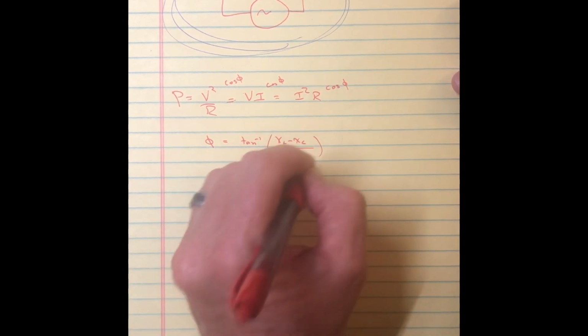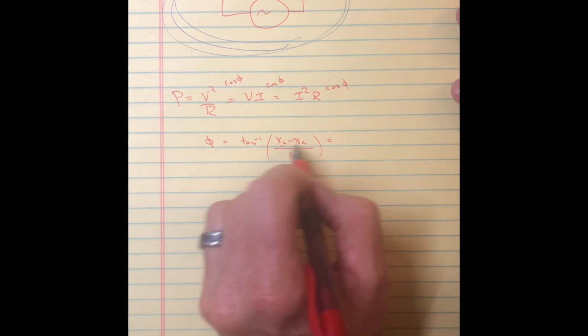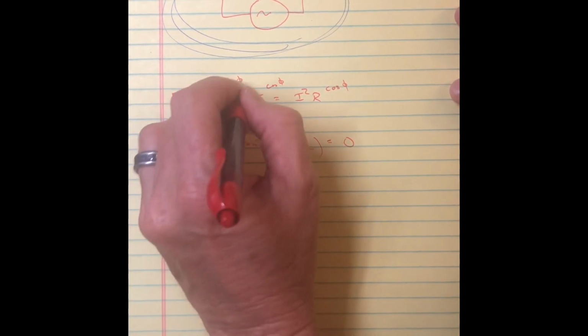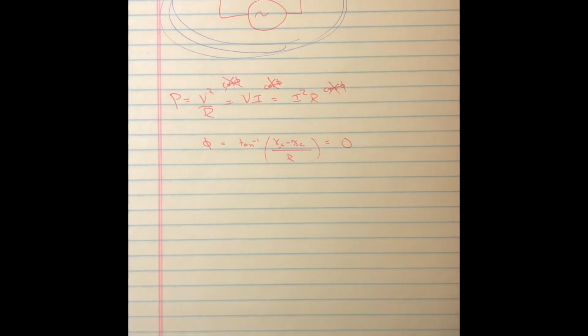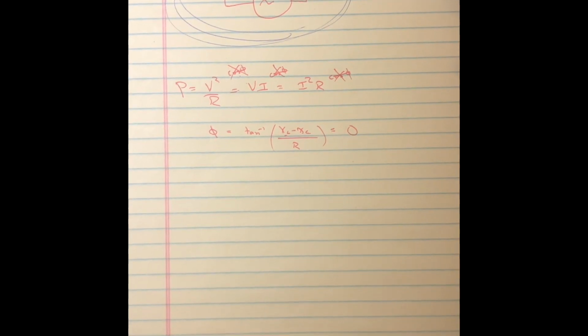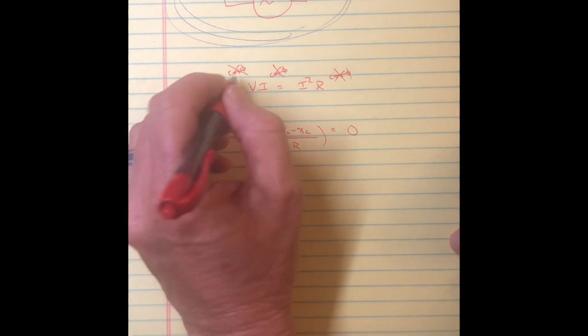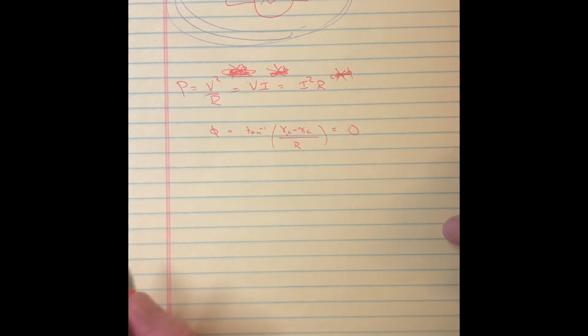Although for this particular circuit, there's no inductors or capacitors, so that's all 0, and cosine of 0 is 1. And so this power factor that I made a big deal over in the lecture, I didn't even consider it for this problem because there were no inductors or capacitors which would cause the current and voltage to be out of phase. And so I just kind of ignored it for this particular problem. But I'll point that out because I think in the problems coming up, I better give that some consideration. So that's kind of an important piece here.